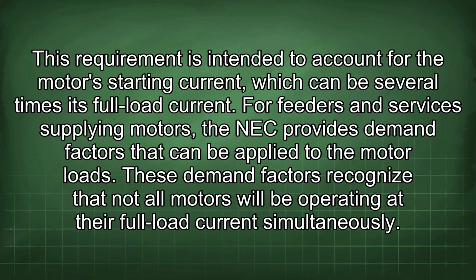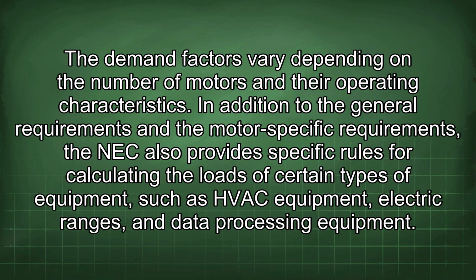For feeders and services supplying motors, the NEC provides demand factors that can be applied to the motor loads. These demand factors recognize that not all motors will be operating at their full load current simultaneously. The demand factors vary depending on the number of motors and their operating characteristics.